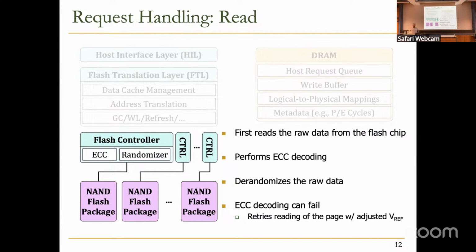Yeah, in the DRAM controller, as you add more decisioning to be more intelligent, that adds complexity. But only changing the metadata in that logical to physical mapping table wouldn't really add complexity, I guess. But decisioning, yes. As you complicate the decisioning that you want to do inside the storage controller, that can complicate it.